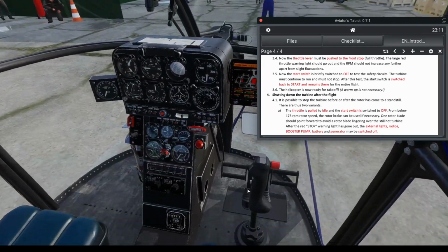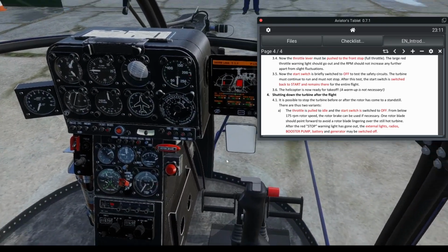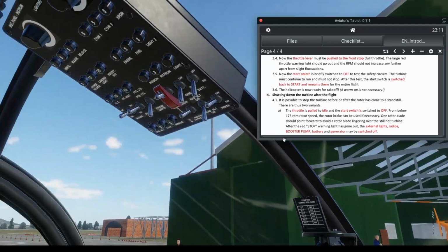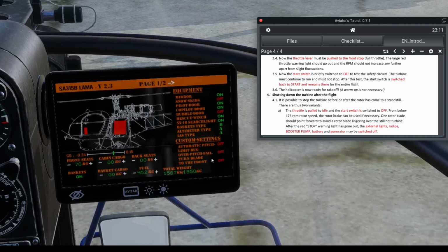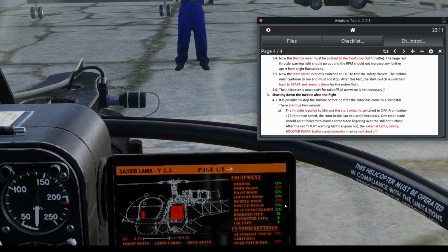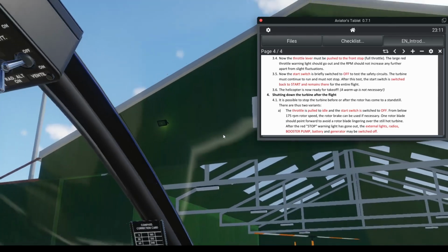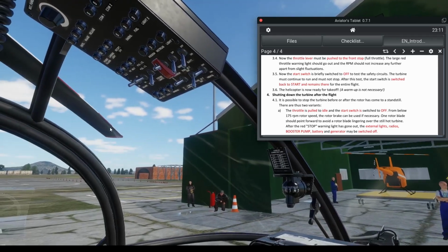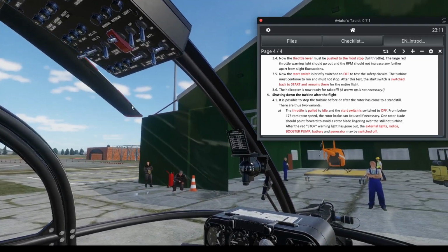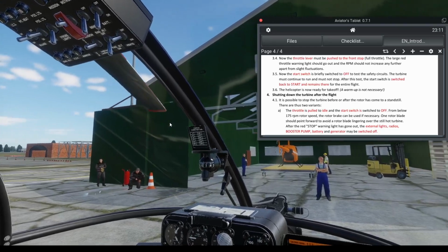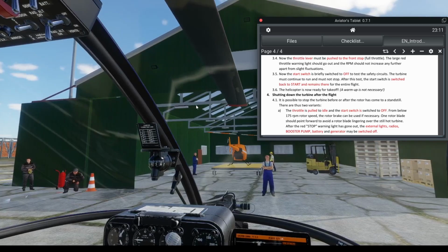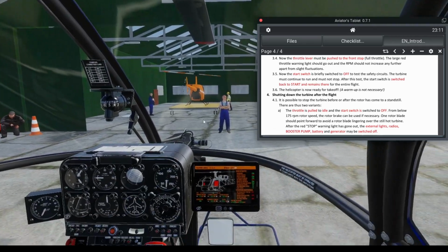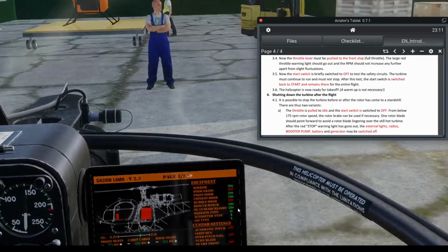Now I'm going to disengage the rotor brake, and let's say you have shut down the helicopter like this. Even when shutting down I will still turn the blade to the front. So just come here, and as long as it's being activated here, it will remain on there, simulating a ground crew turning the blade to you. One blade has to be in front, just like this, and it will go back to off.